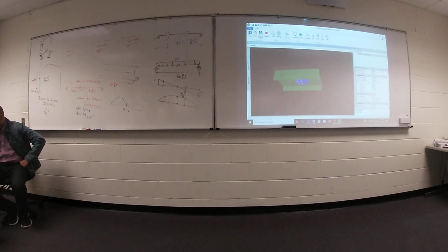Until now, under the effect of your shear force equal to 60. Let's try another value. 30. Fail. 10. Still fail. Something is wrong in your connection, maybe not related to your load. Another thing I will show you. So keep it 60 and let's see. Okay. Maybe the number of plates, we figured it out. Hole type: what is the type of your hole for bolts?